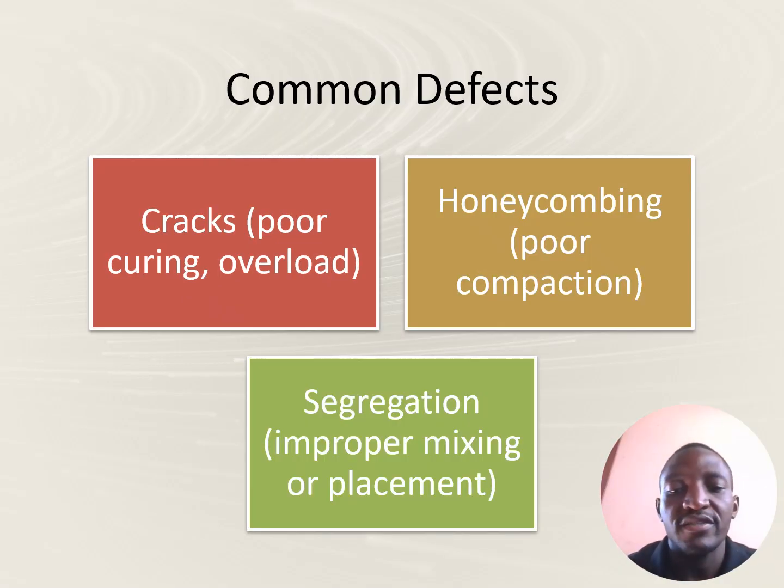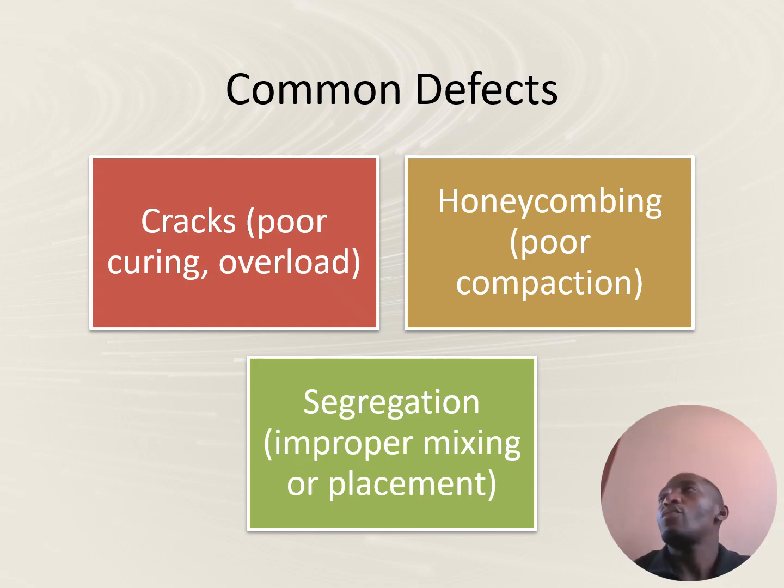Let's look at the common defects. If you don't follow proper curing, you're going to experience cracks, from poor curing and overload. Honeycomb, from poor compaction. If you don't compact your concrete properly, you're going to experience honeycomb. And the last one is improper mixing and or placement.